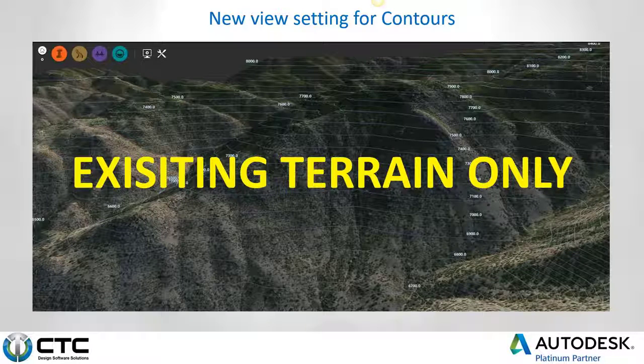If we bring in a raster image for terrain, that will be considered terrain. If we build something using the coverage area or the land use area, that's going to be considered design and will not come through with the contours. If we build a corridor, that will not come through with the contours. It is existing terrain only.